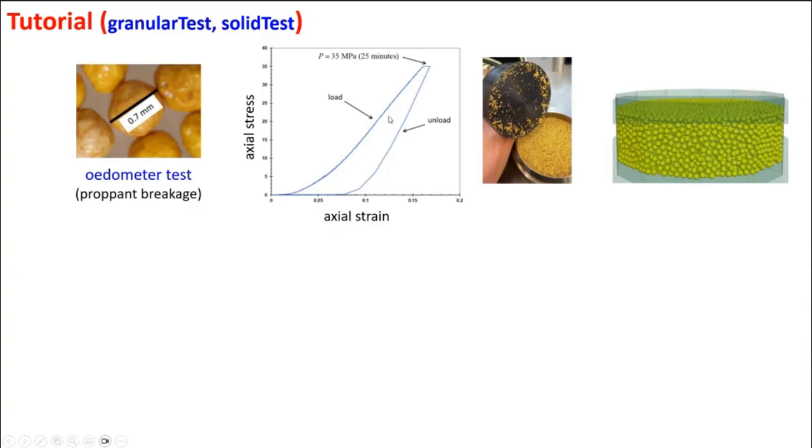And then we can plot this, right? And so here you see loading. It's taking more and more stress. There's a time dependency here where they actually hold the platen, don't let it move, keep the stress constant. And you can see it continues to move a little. And then we unload, and your stress goes down, comes to here, right?